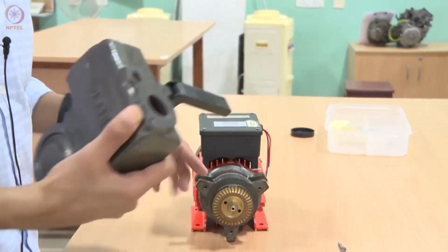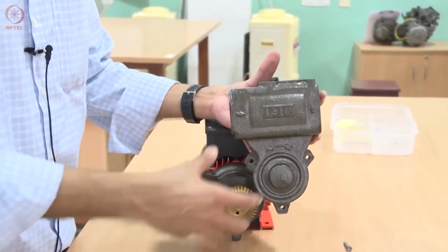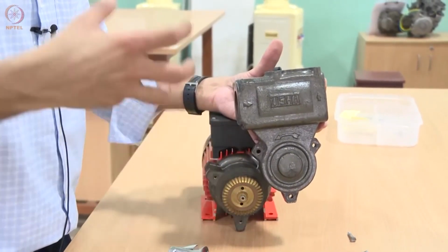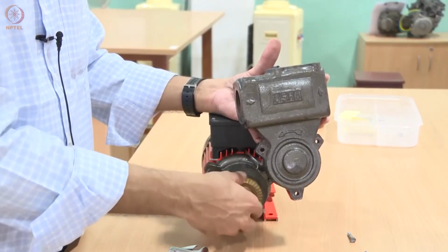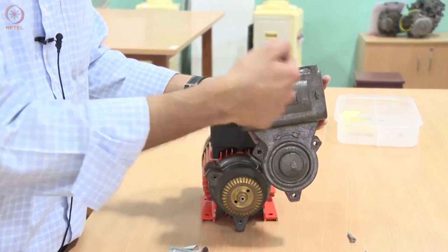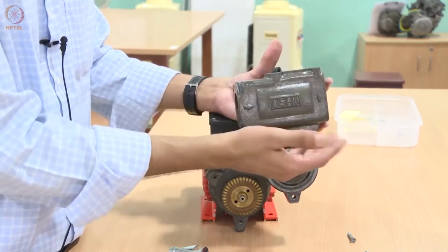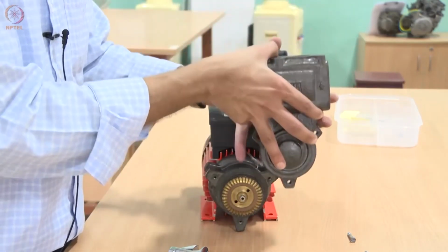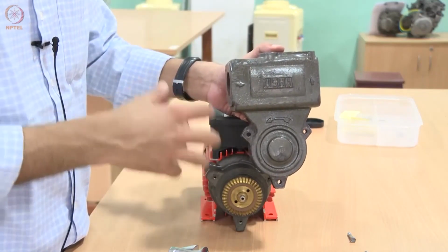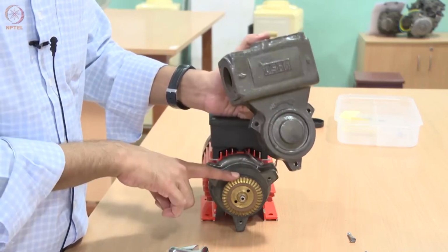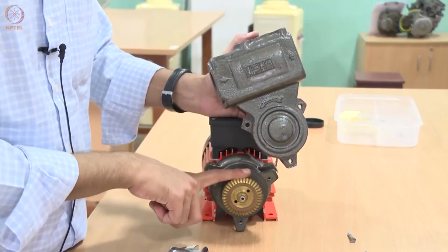The feature of this design is, by continuously circulating the water, little by little, the pump will evacuate the air that is in the suction line. After you run the pump for maybe a minute or so, the water will keep circulating and slowly suck out the air, and the water, because it is dense enough, will keep falling. So water will not be discharged initially. Once the entire suction is fully drained of all the air and is filled with water, the pump has primed itself. That's why we call it a self-priming pump.